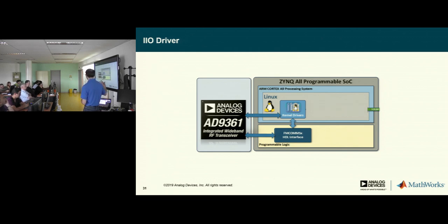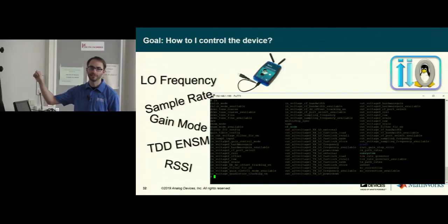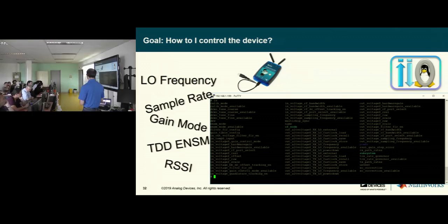Now, this driver, as I mentioned, is living in the kernel on the device that that hardware is connected to. So this is in the kernel of Pluto itself. And this is controlling the transceiver and moving data back and forth. But using these attributes is a little non-ideal because you have to SSH onto the board, cat and echo all the settings that you want to change, which is great for a driver maintainer or developer, but for a user, it's kind of painful.